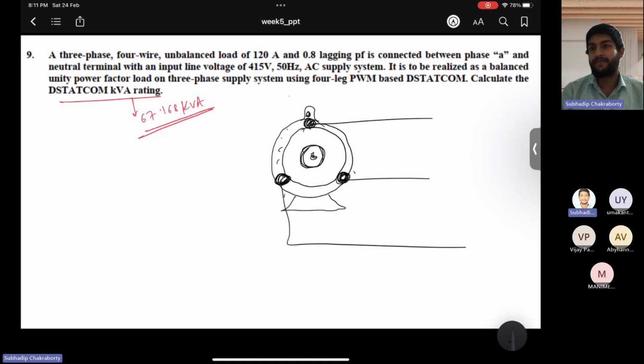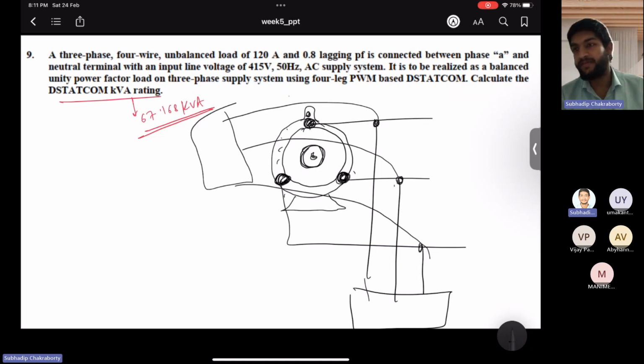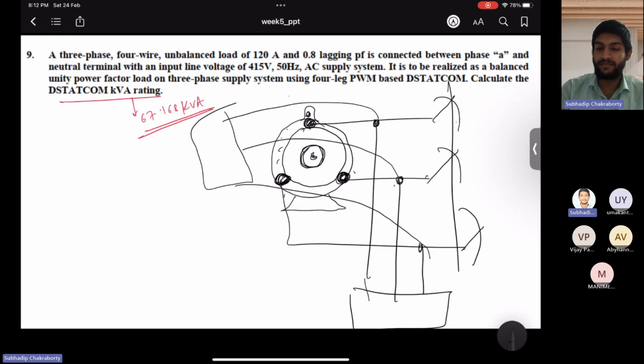So you have the three-phase supply, and it obviously needs some reactive power excitation requirement. So we connected the DSTATCOM as a source of reactive power. You may have seen papers where we can connect capacitor banks to provide constant excitation. With some small voltage across those capacitors, they can initially push some reactive power, and we rotate with the prime mover, and then it will generate. Once it generates, you connect with the load. First you generate the voltage at no load. Once it is done, then connect the breaker, and this is the load.